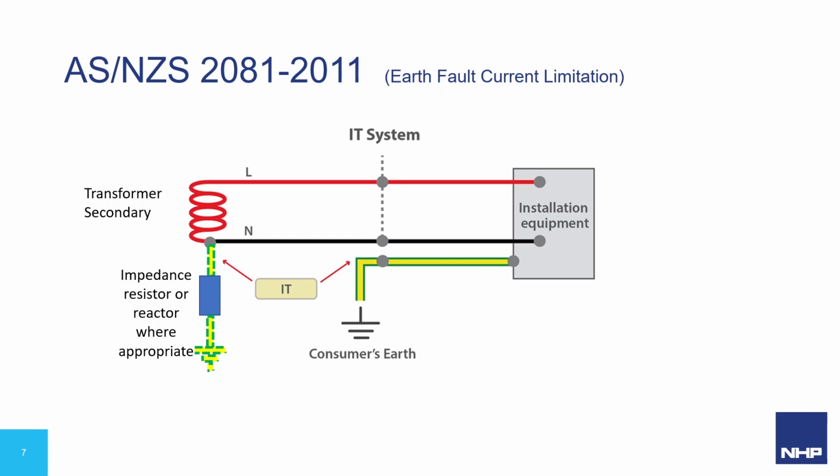The earth leakage relays placed in the reticulation system have specific requirements and must constantly check and recheck the occurrence of earth leakage current, as well as their own connections, their own performance and their accuracy, and also check for the system warning and lockout integrity.